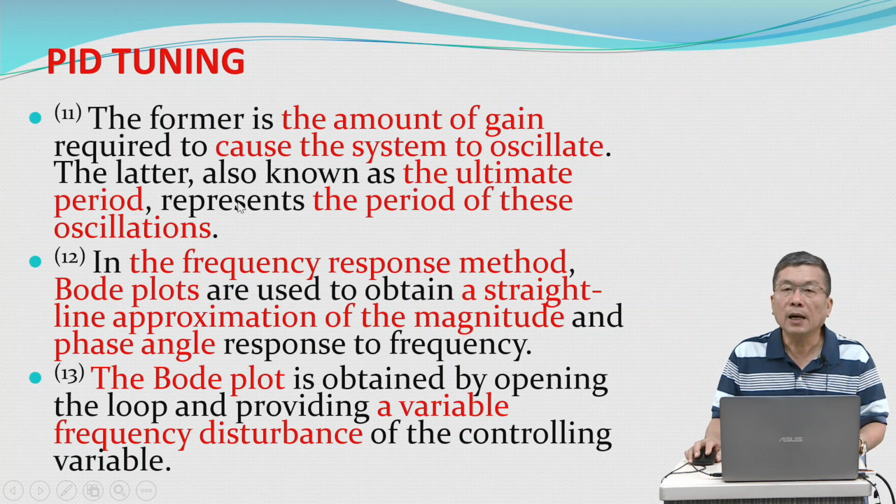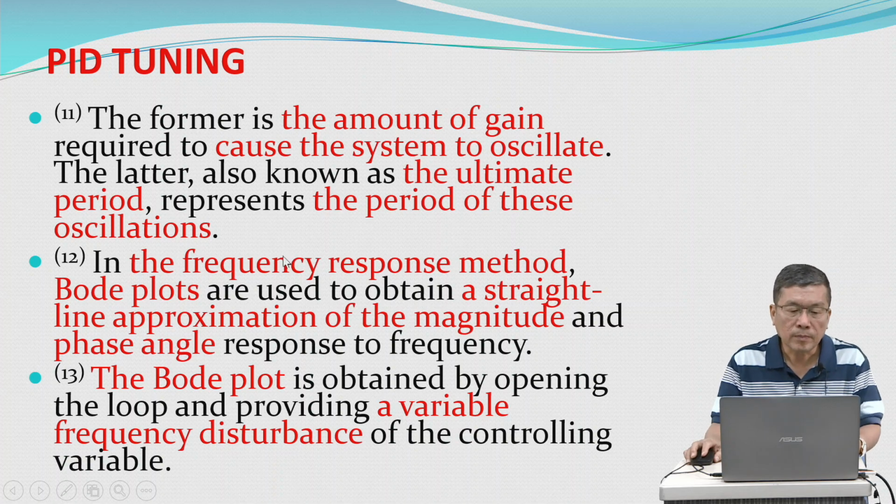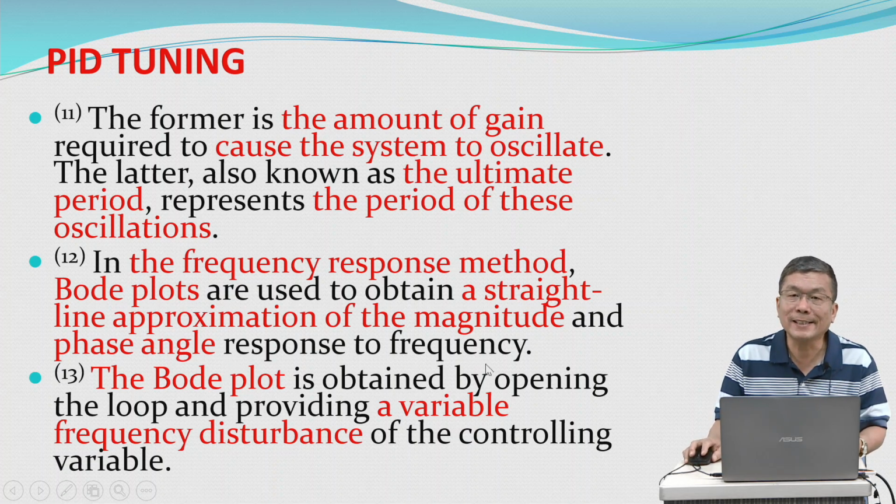The latter, also known as the ultimate period, represents the period of this oscillation. In the frequency response method, Bode plots are used to obtain a straight line approximation of the magnitude and the phase angle with respect to frequency.